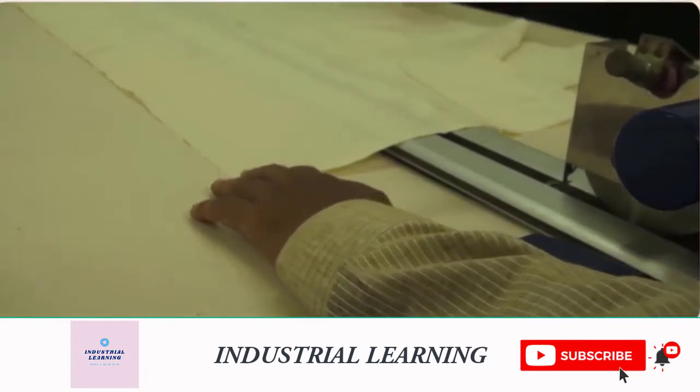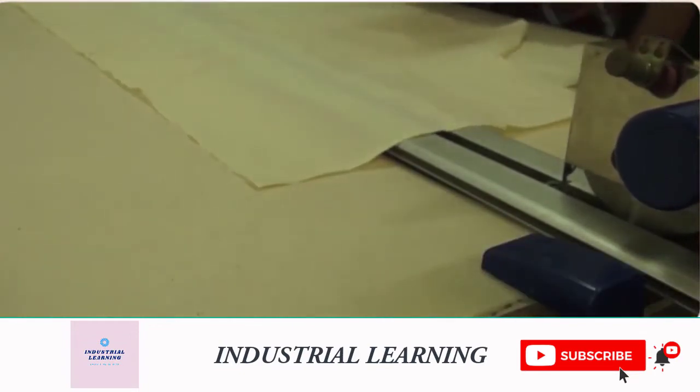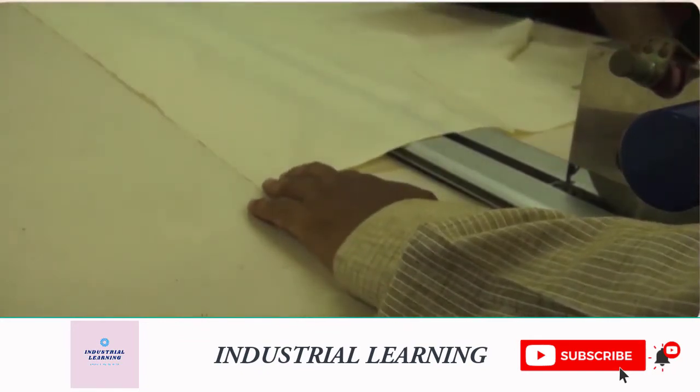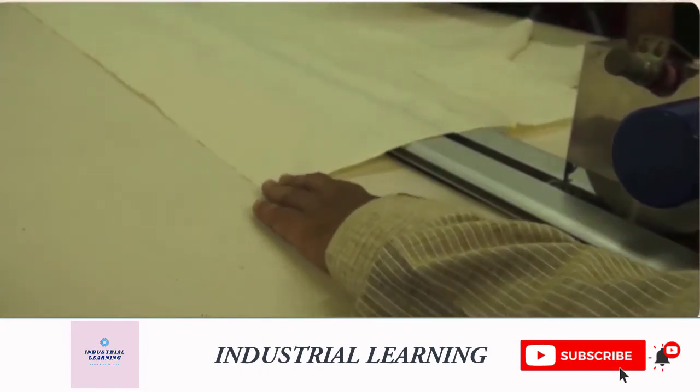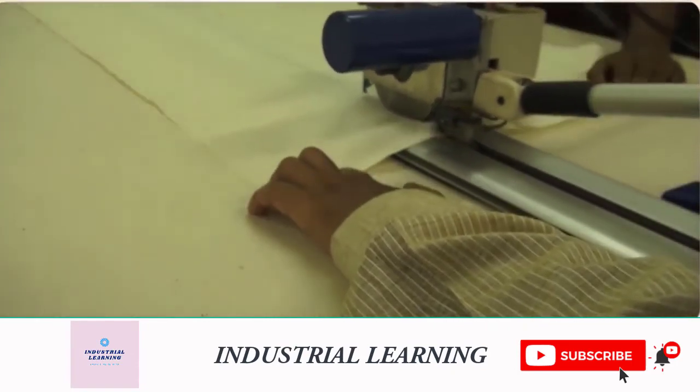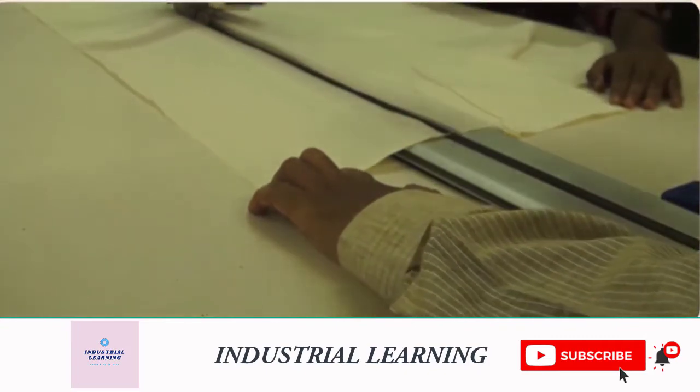At the end of the spreading process, the extra fabric is cut away by the end cutter by pushing the knife through the rail using the handle.